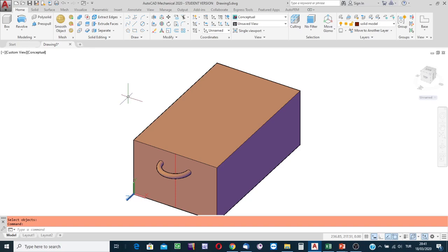It is the characteristic property of the second revolved feature. You see, at present, there is no plane to draw the profile at the symmetric cross section of this rectangular prism, so it must be created.